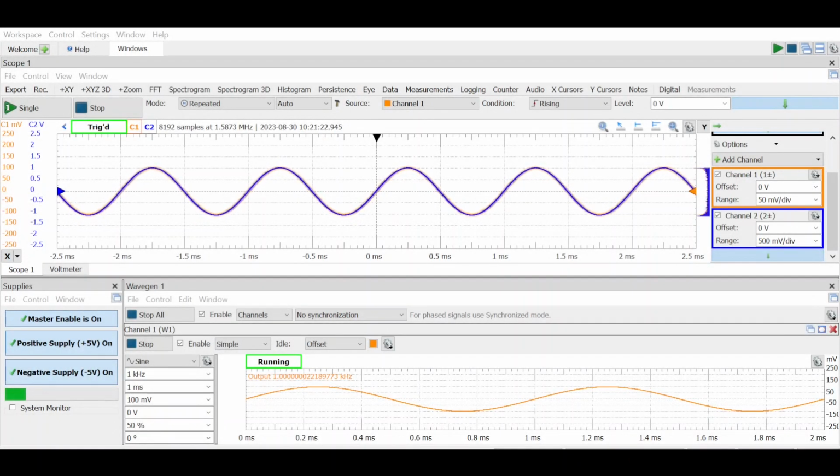Once again, we'll be using the waveforms software, which is used to drive the Digilent Analog Discovery. This is the power supply section here, the waveform generator, and the oscilloscope. Currently, the oscilloscope is looking at the non-inverting op-amp. You can see that the waveform generator is providing a 100 millivolt signal. That is a peak voltage. You can see that in the oscilloscope here. Here's 100 millivolts, so that's 100 millivolts positive and 100 millivolts negative,